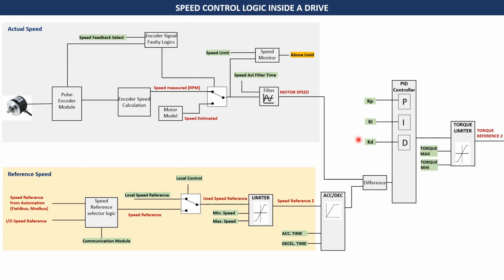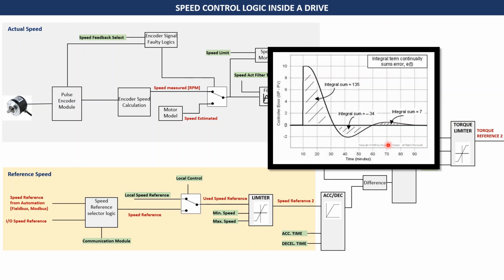and again the differential gain gets multiplied with the differential of the error signal to generate the output. This part of the controller helps to improve the transient response of the controller. Transient means the time the signal takes to settle to a steady state. So this is the transient time in which it is fluctuating like a sinusoid, and once this reference meets actual, this is the steady state. So the time it takes to meet this steady state is called the transient timing, and KD helps